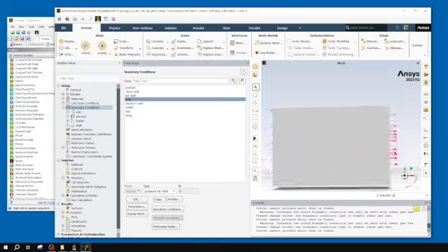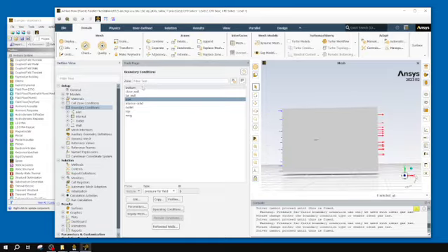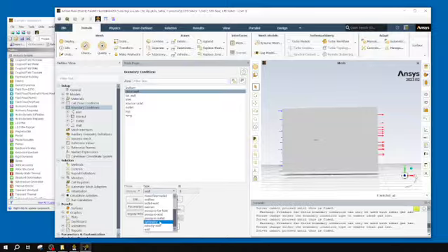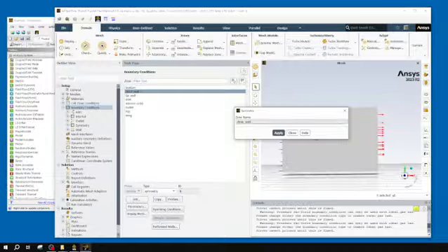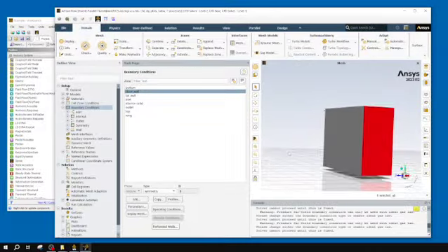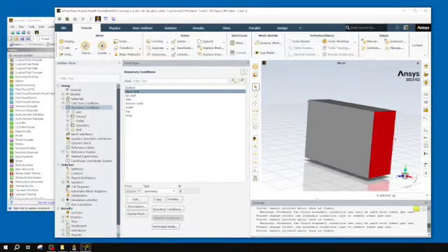So the last wall I have not actually defined is my close wall, and that's because I am using a symmetry boundary. So I can just come down here, click symmetry. You can see there's nothing to kind of mess with there, and I can click apply. What symmetry does is it enforces a mirror condition. So as you saw, I only imported half my wing rather than a full wing.